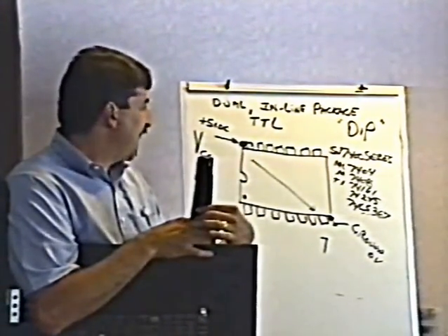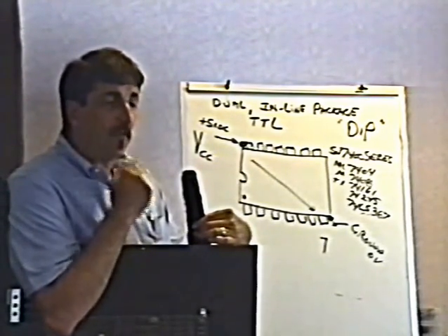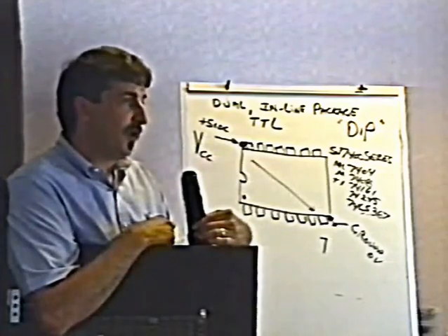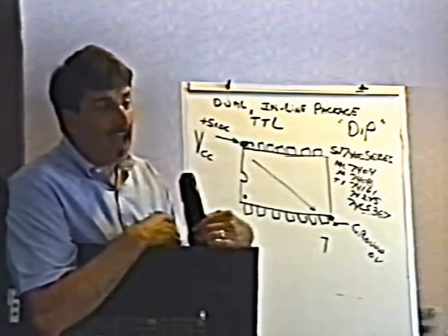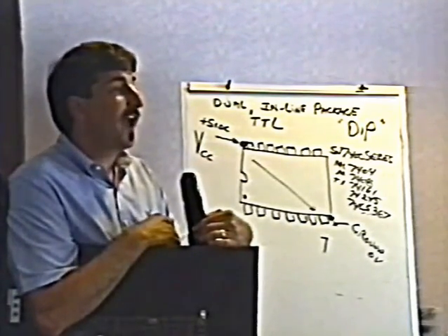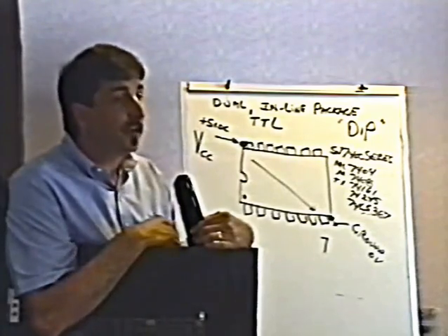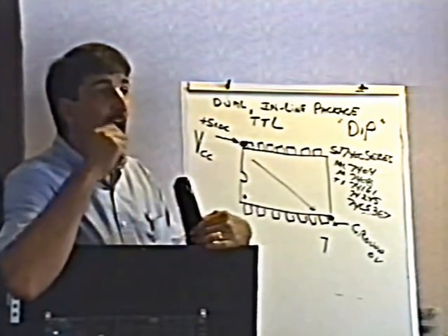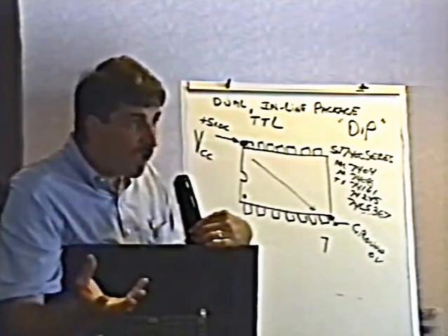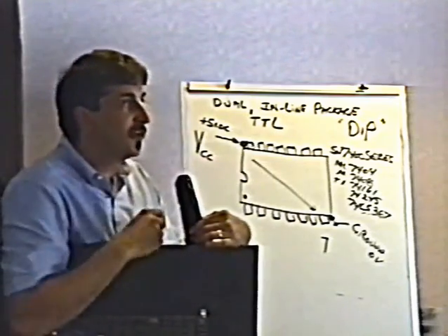And as a matter of fact, and this is pretty important, so try to remember this, sometimes you'll have a weird power supply problem where the 5 volts really does seem perfectly okay. When you measure it with your meter, it's 5.1 or whatever. But you have, I guess the best way to describe it is as a hidden power supply problem that your meter cannot locate for you. Sometimes power supplies put out a huge amount of electrical noise that your meter just doesn't see. An oscilloscope would see it, but your meter doesn't.